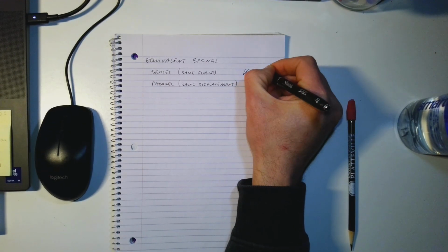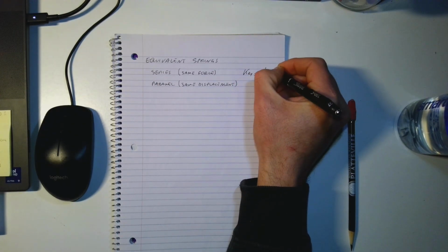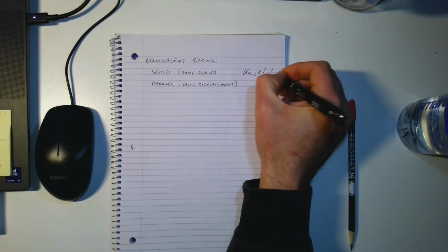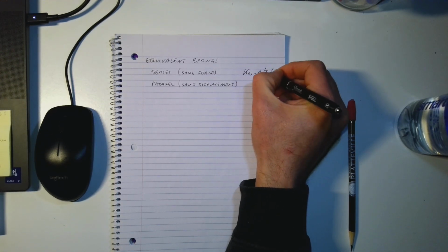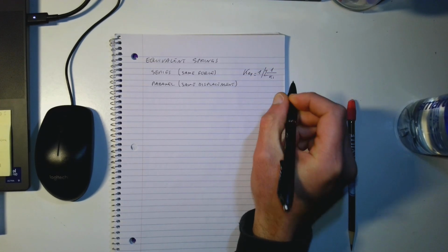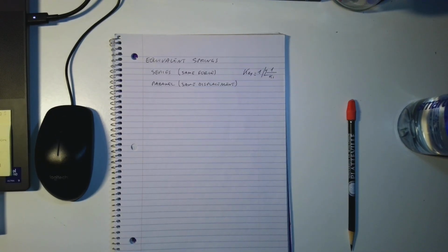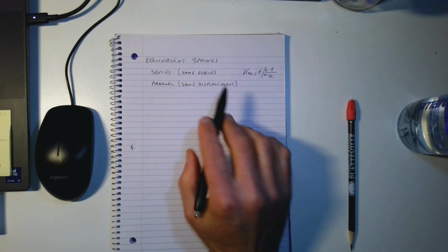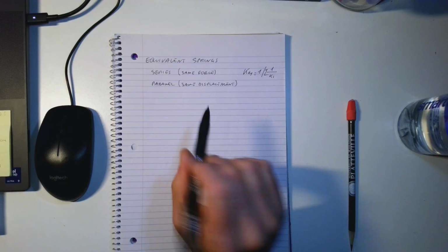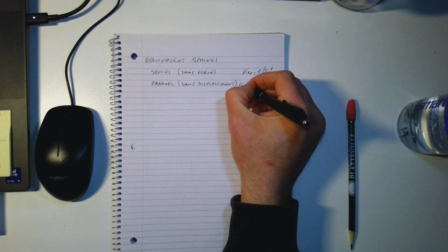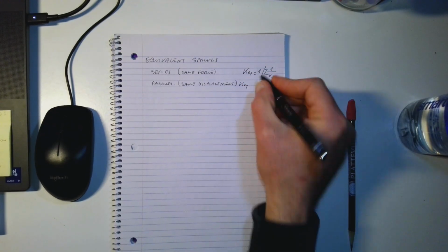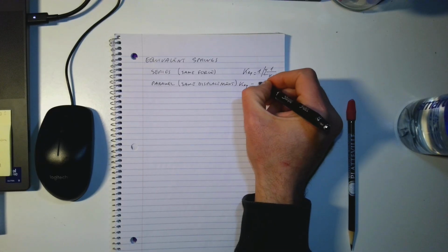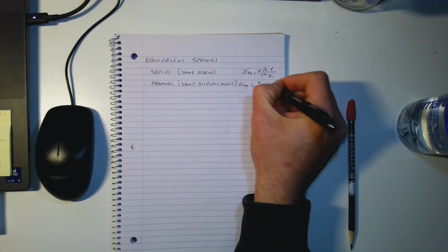So when we look at springs in series, the equivalent constant is equal to 1 over the summation of 1 over k_i. Again, this is valid for as many springs as we want. When we have parallel springs, the k equivalent would be equal to the summation of k_i.